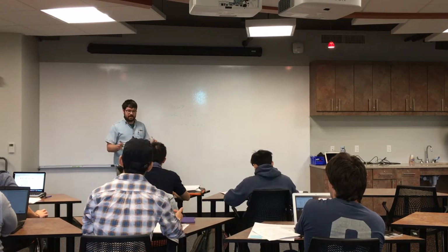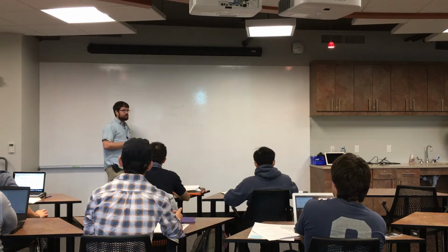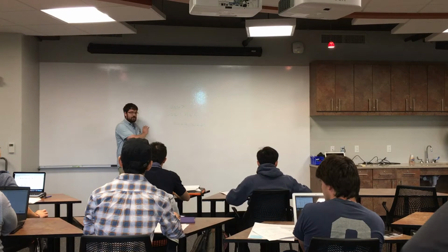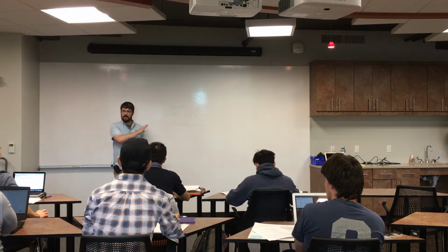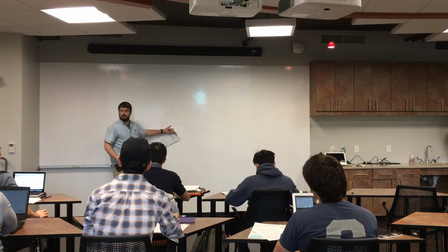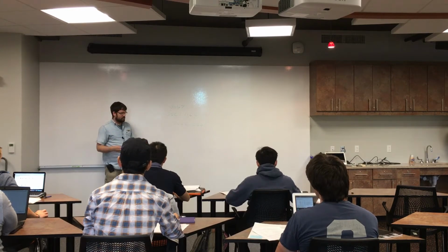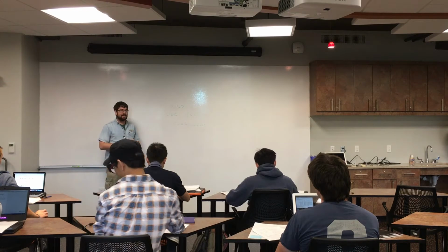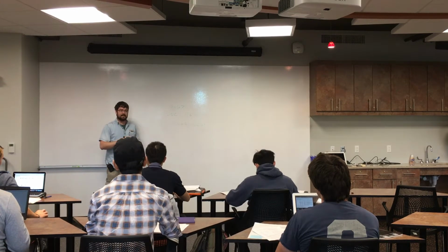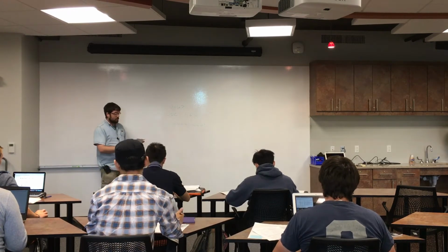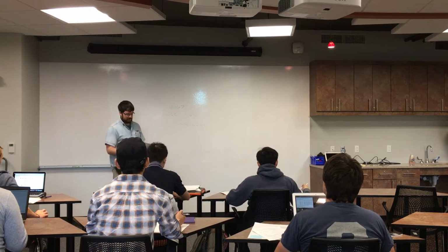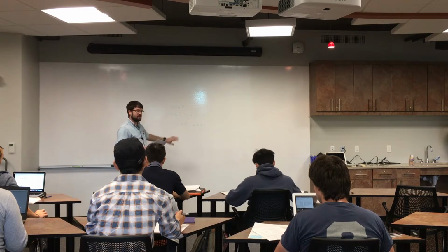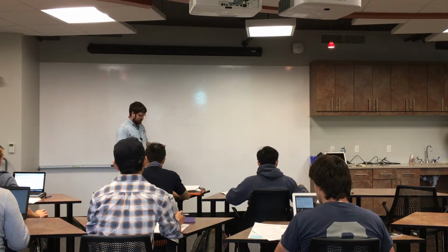So if you see stuff that's happening in your projects, this could happen on your Arduino. I've seen it in some firmware systems that I've done as well. Right, after a certain number of seconds, something always happens. Look for counter rollover. This will get you. On a processor that I commonly use, it's like 53 point something seconds is the counter rollover period. And so if I mess up, I see these weird 53-second cycle glitches. So that was the point of that problem, was to show you that counter rollover exists. But everybody was technically right by adding a 9th bit. We just don't have 9-bit processors, so you'd have to go up to a 12 or 18-bit representation.